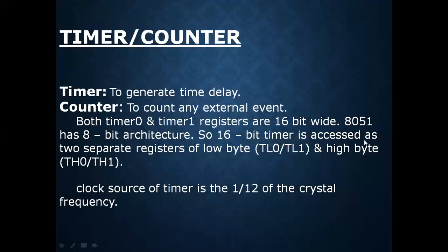Okay, so today we will discuss this timer or counter operation. In the 8051 microcontroller, we have seen that there are two timer or counter operations, and these are complementary operations. At a time, we cannot do the timer operation as well as the counter operation. The timer is used to generate the time delay, and the counter can be used to count any external event. So for counting the external event, we can use the counter.